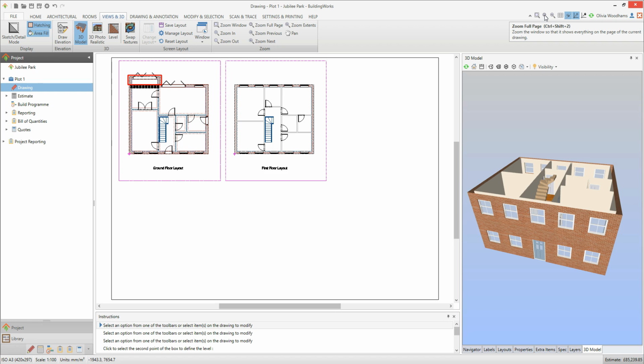The attic level should be drawn with a wall height of 0. The walls have already been estimated on the first floor plan. You can then draw the roof on the attic level and add all of the attic components.